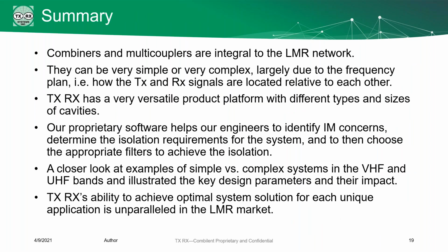In summary, combiners and multicouplers are important parts of the LMR network. They can be very simple or very complex. The number of channels isn't always the biggest factor in cost. A difficult 3-channel system can cost 10 times as much as a simple 6-channel system.